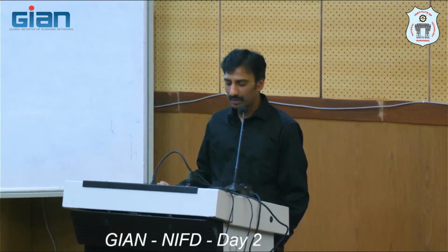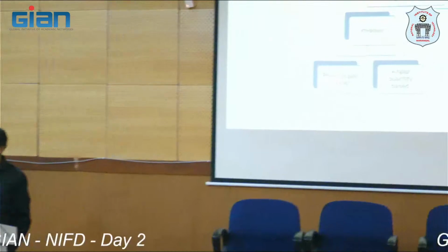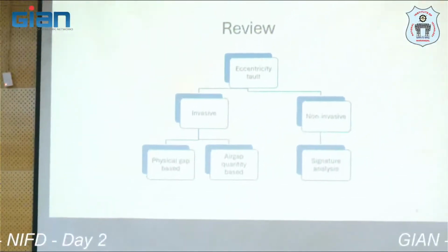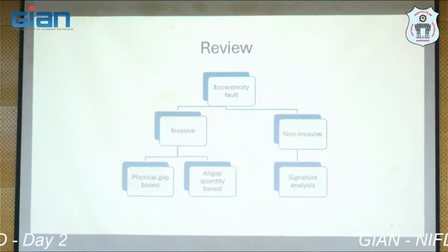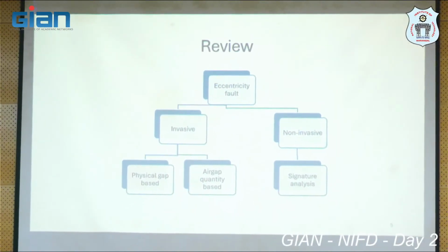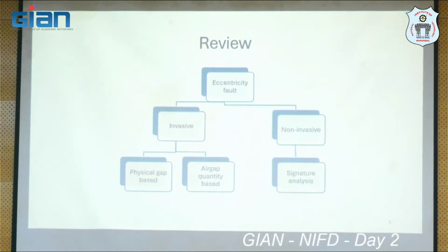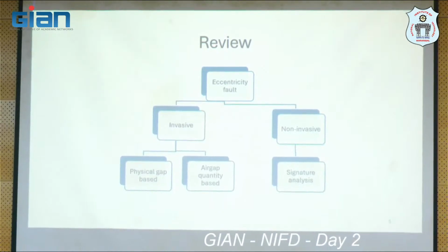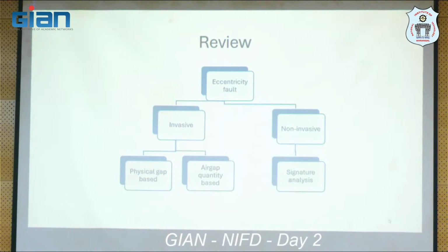Then I talked a little bit about different approaches that are traditionally available to diagnose eccentricity faults. They can be broadly classified as invasive techniques and non-invasive techniques. Invasive techniques use sensors inside the motor, and non-invasive techniques use sensors outside the motor. So they are all sensor based. Where the sensors are located makes the difference.